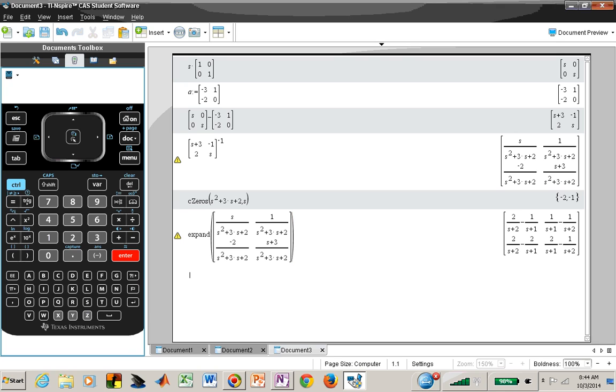There's my partial fraction expansion. 4 different pieces. Pretty quick. Now you just have to make sure that you keep track of things, but now that's telling us a lot. When we found the roots of that denominator were minus 1 and minus 2, what do you physically start seeing or mentally start thinking about? It's stable. In the time domain, what are you seeing as far as modes or expressions?